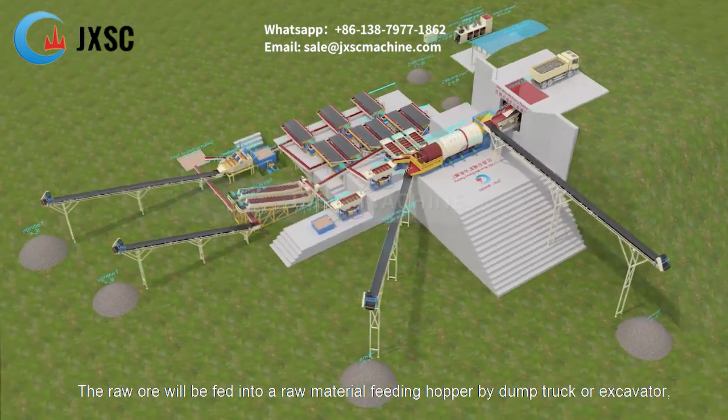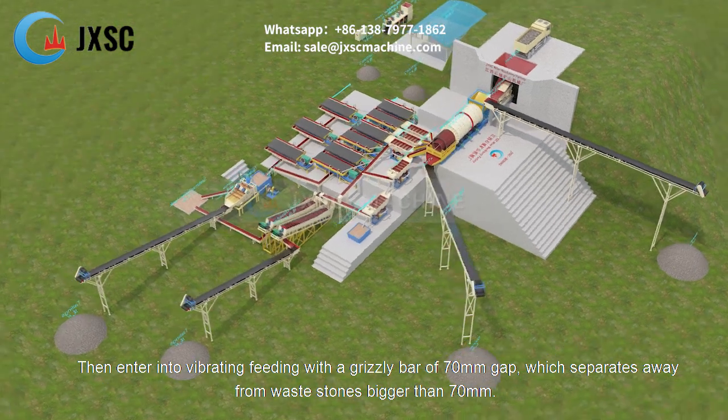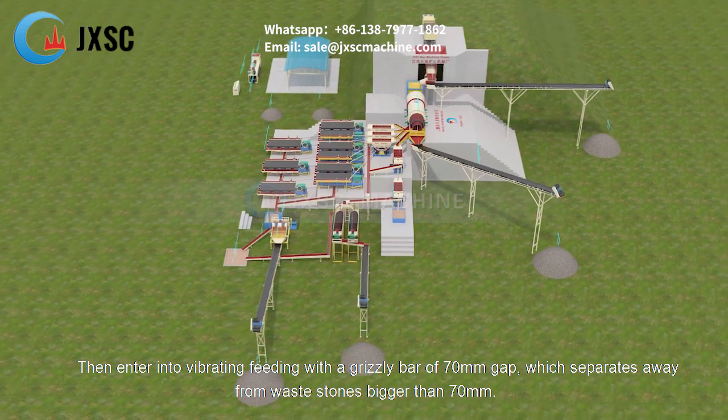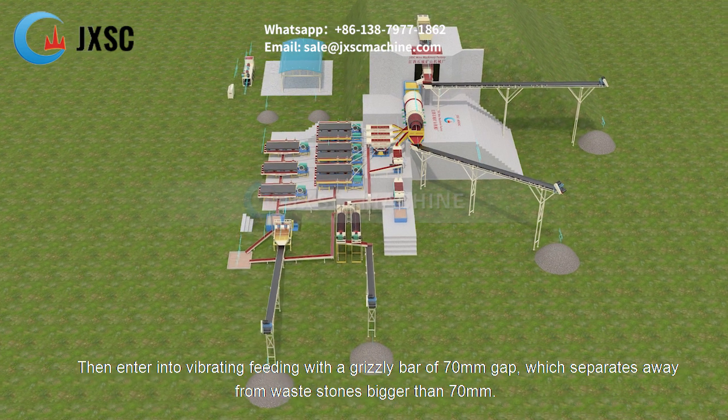The raw ore will be fed into a raw material feeding hopper by dump truck or excavator, then enter into the vibrating feeder with a grizzly bar of 70 mm gap, which separates away waste stones bigger than 70 mm.